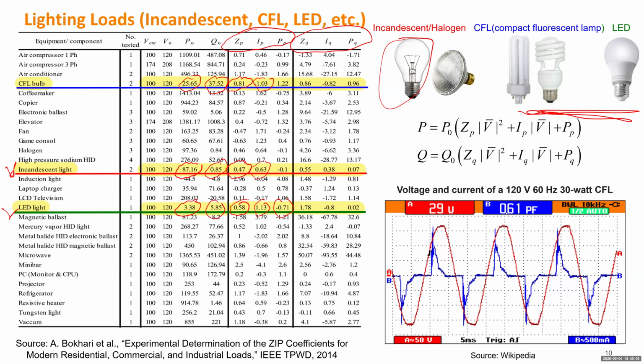I use this example to explain why those energy saving lights can have very large reactive power. What does reactive power really mean? If you draw the voltage waveform at this bus or substation, that voltage waveform can be controlled by a controller. If it's next to a generator, the generator will generate a perfectly sinusoidal waveform, if it is designed well. Then when you connect a load to this bus, the voltage cannot be changed significantly, but current can change. Current is generated by this specific device. If the current has a very similar sinusoidal waveform, in exactly the same phase, that's power factor 1. If that current waveform is lagging the voltage by any angle, that's not power factor 1. Also, even if they have the same phase, which means they reach the peak value at the same time, but the waveform looks very different, that's also reactive power.